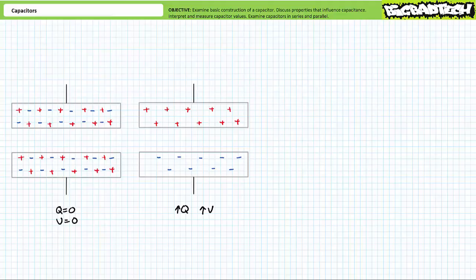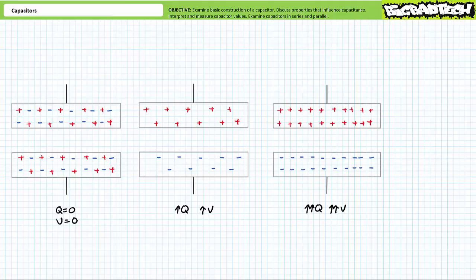The charge imbalance between the plates of a charged capacitor establishes a resulting voltage differential. Understandably, the greater the charge imbalance, the greater the voltage between the plates. It can be said that charge concentration directly influences voltage. More charge, more voltage. Less charge, less voltage. Theoretically, an ideal charged capacitor will maintain this charge imbalance indefinitely because the non-conductive insulating dielectric inside the gap between the plates prevents current flow and charge equalization. In practice, a real capacitor will exhibit a tiny amount of leakage over time and cannot be expected to maintain a charged state indefinitely. For now, let's just assume this is an ideal capacitor and no leakage occurs.